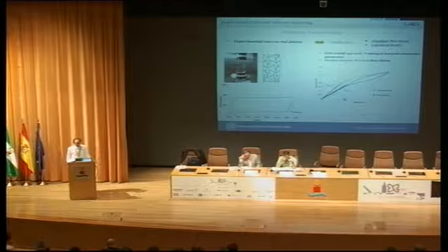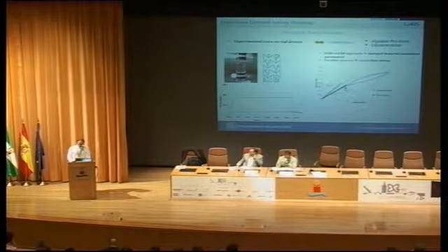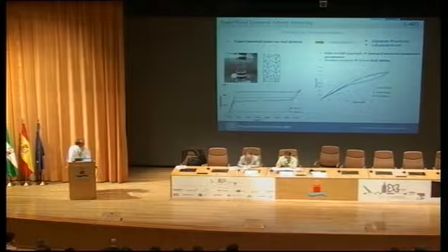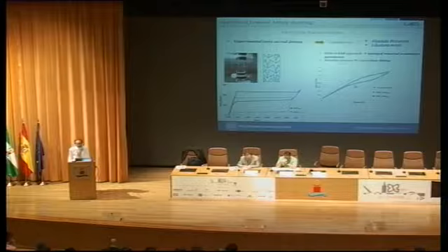So apart from the displacement at the end, which is imposed in some way, this is correct, but for the rest we are not satisfied. So with manual tuning, we modified the constitutive law, the stress-strain relation, and what we obtain is a quite perfect superimposition of the two curves. Okay, we have identified the material.